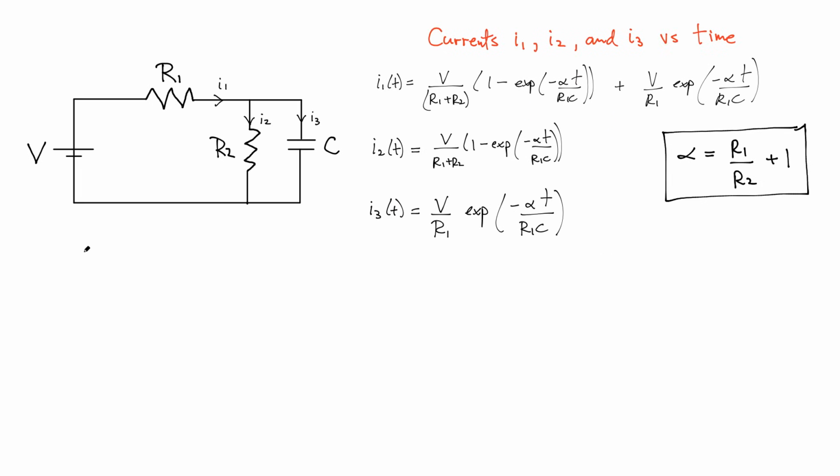And it's worth taking one more limit actually. What happens if R2 is very, very big? Imagine somebody just went up there and just cut the wire. Well, if somebody cut the wire, basically the resistance goes to infinity. Let's actually just get rid of it. There shouldn't be any current flowing through that section. So if R2 goes to infinity, this is what we get. Now, what do the expressions look like?